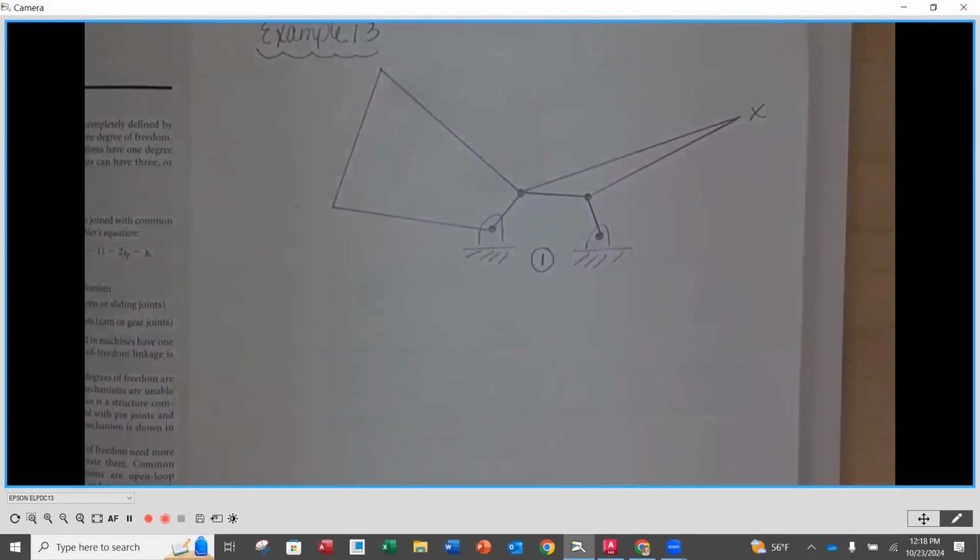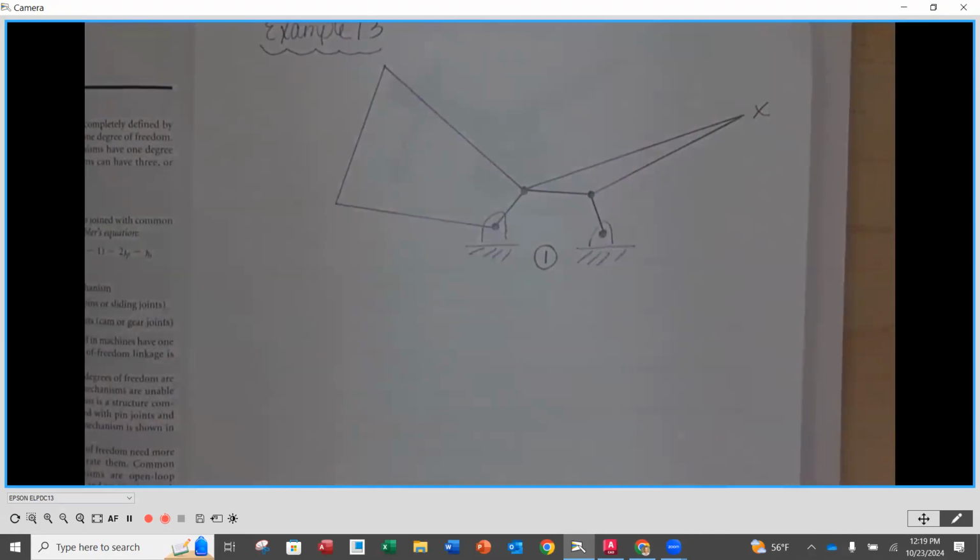And remember, even though it's two separate connections, in this case, it is the same part, but it can be physically different parts. It just means that that point is not moving. That connection to the mechanism is not moving. And all of it, whether it's two separate pieces or not, it's still considered just one link, which is the frame.